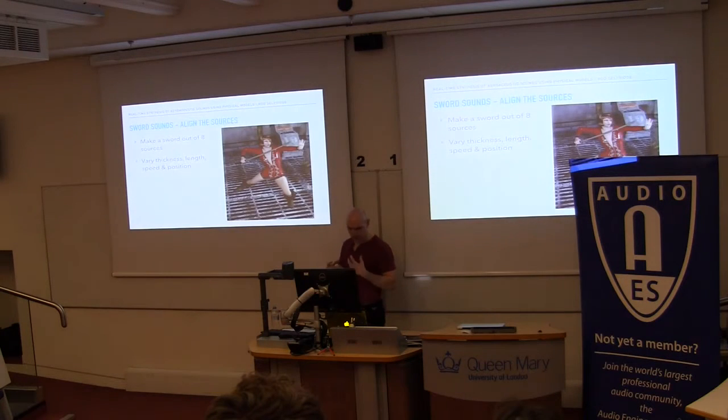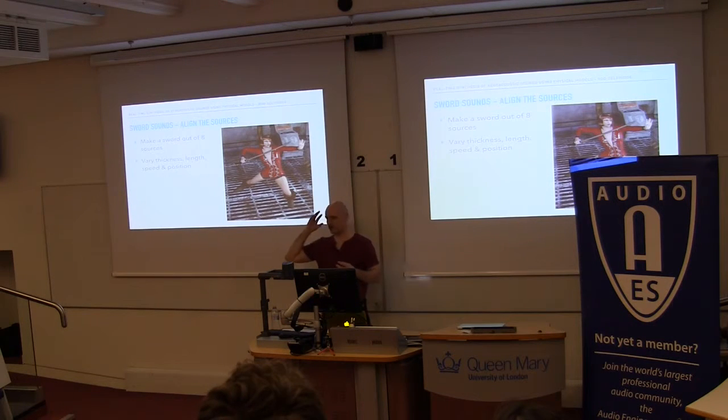But what I did was I put 8 different compact sources in a row, the majority of them at the tip, then spaced back down, and a couple more further down. The reason they're at the tip is because the tip moves much faster, and that's where the majority of your sound is generated.